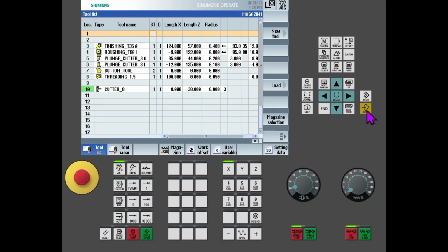Then press input. After pressing input, the sister tool and the cutting edge position both become one, because no other tool of this kind is available in your tool list. If you find another identical PCLNR 2525 M tool over here, the sister tool becomes two. But since only one tool is over here, the sister tool is only one. And D is the cutting edge position, or cutting edge number, that we will discuss later.